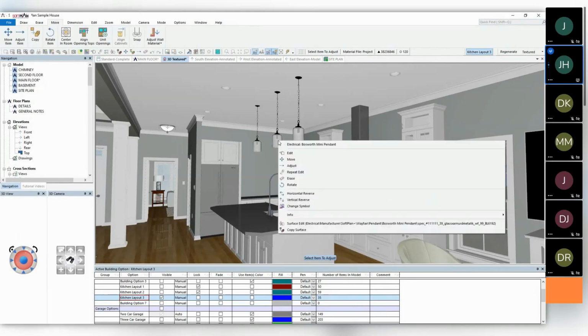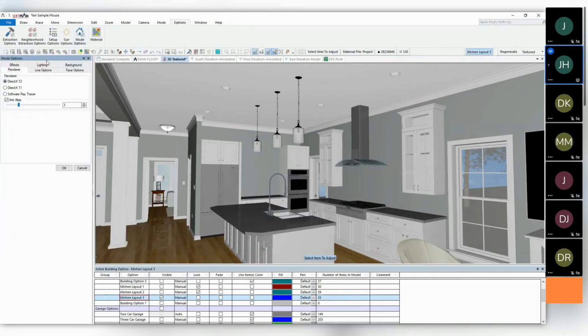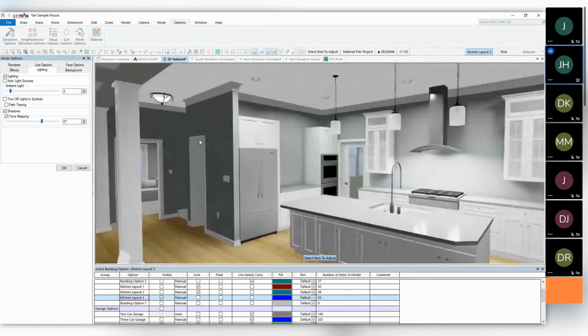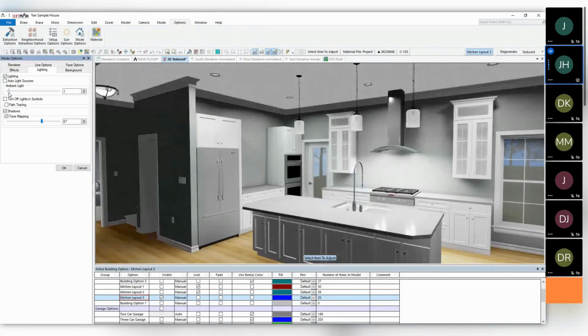And this will give you a much more realistic, so I'm just going through and repeat editing this within 3D, but it will give you a more realistic shadowing and so on with the model itself. If you're going to do this as far as your lighting is concerned, then certainly under the mode options, you're going to want to not have your brightness turned up artificially, but instead you'll be using the actual lights within the model to light this itself, as opposed to what I had earlier where I was auto lighting the entire model itself. So this ambient light, I can turn that down.